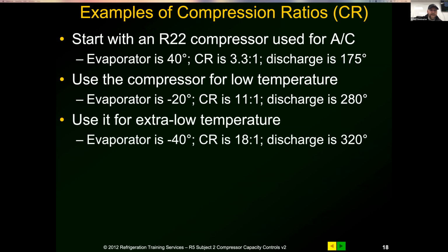A question I like to ask guys when you're doing compressor startups: you need to do a compression ratio check. A lot of times, if you're going out on a repeat call, the first thing we always say is, oh, it's under warranty, must have been a bad compressor. Well, I'm going to tell you this from the field: 9 times out of 10, we didn't do a check down. We didn't check the voltage, the contactor. We had a restriction, something, and we had an excessive compression ratio, which caused it to overheat.